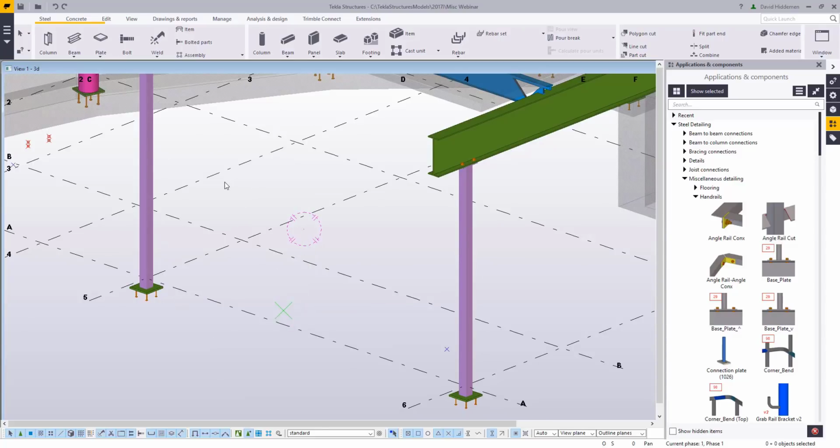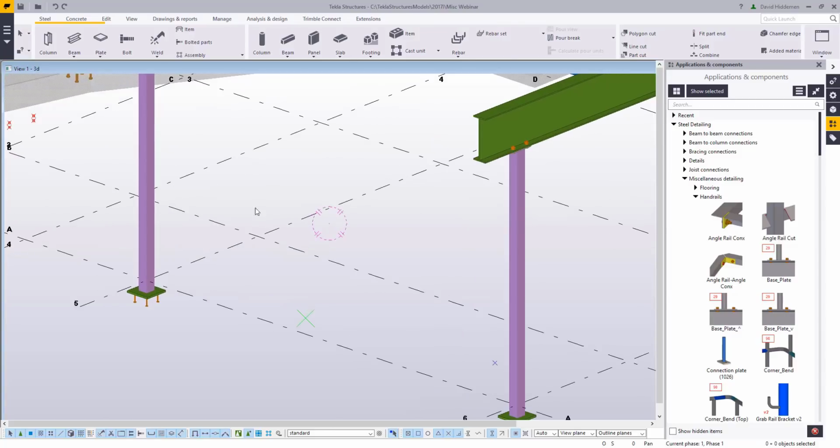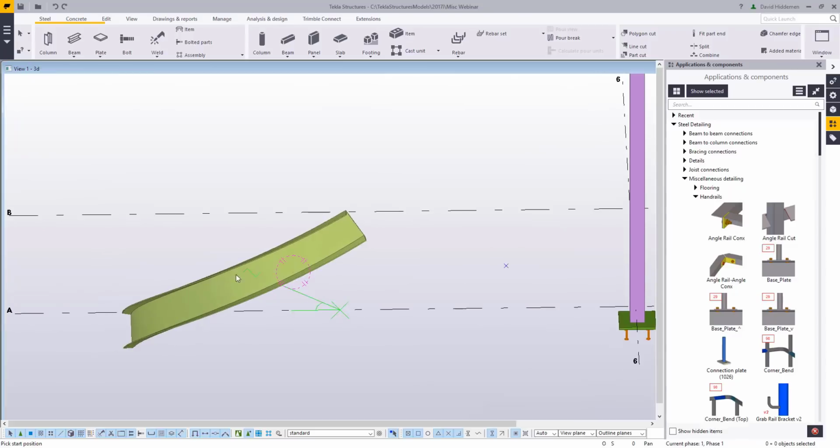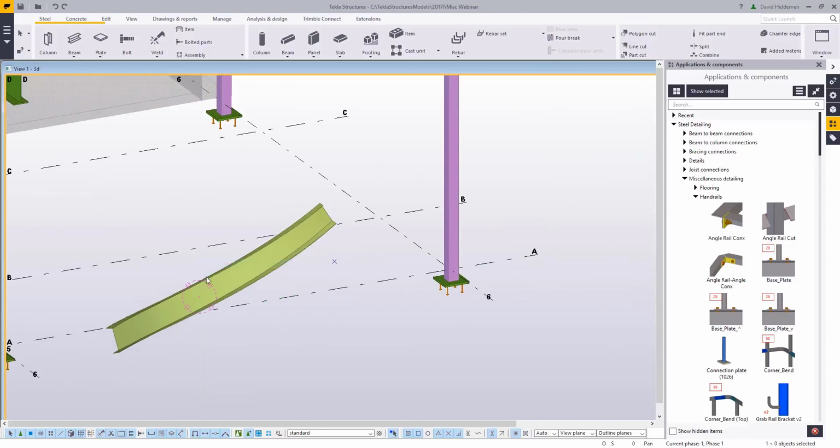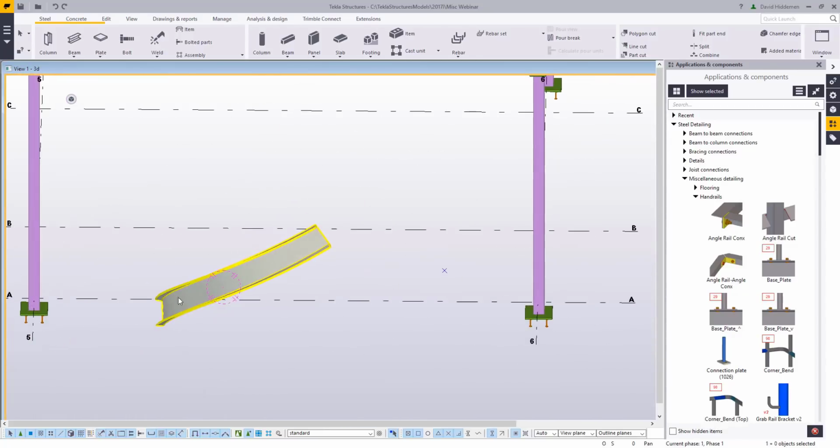Now, if you're doing something with an extruded shape, like a channel or a tube, we have a spiral beam command. A spiral beam works by picking 2 points, basically setting my radius, and then finally I middle mouse click and it will create, in this case, a spiral channel. Again, maintaining web vertical throughout.